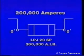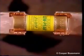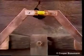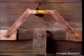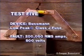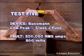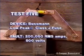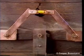It will illustrate what happens when a fuse is shorted out at its terminals when very high fault currents are available. Modern current limiting fuses may be tested at fault levels up to 300,000 amperes RMS symmetrical at rated voltages. In this test, a Bussman low-peak Class J fuse will safely open a short circuit with 200,000 amps available. The fault was created directly at the terminals of the Class J fuse.